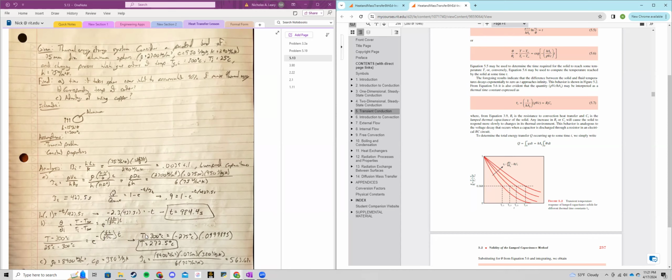So just rearranging that equation, we get our top portion is equal to the difference here, which is negative 275 degrees C, times 0.0999895, which is just this term. Then we can multiply these and add 300, which gives a temperature of 272.5 degrees Celsius. So the center of the sphere, after our 984.4 seconds of heating, goes to 272.5 degrees Celsius from the 25 originally.